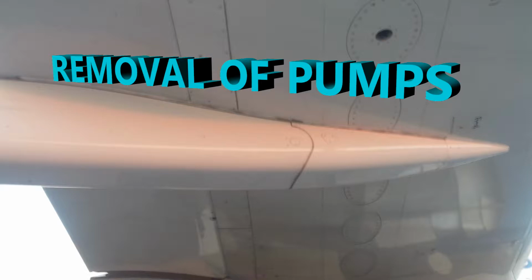Okay, now the whole idea with having a canister, because why even bother? Why not just keep the pump there and install the pump and not worry about it being installed in a canister? Well, the reason is because you're able to actually replace it without having to drain the entire fuel tank. Okay, so that's kind of nice, right? If you have a separation of that and you can just replace the pump. So that's what that is.